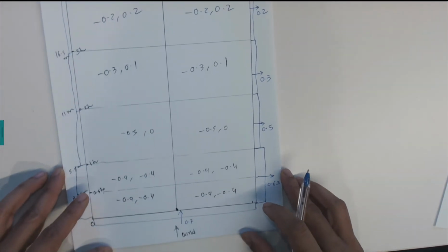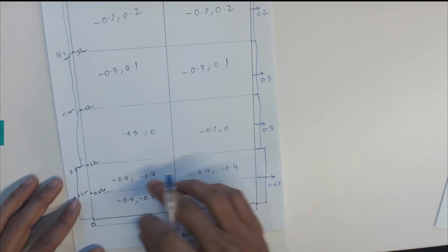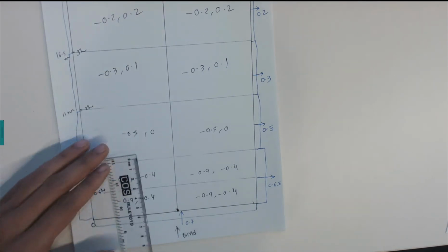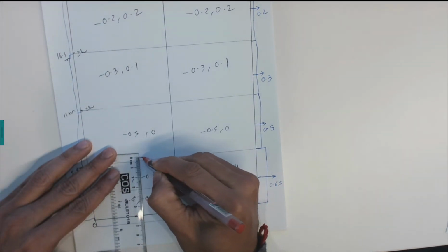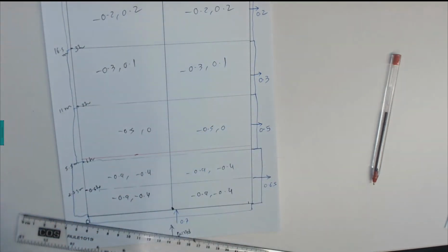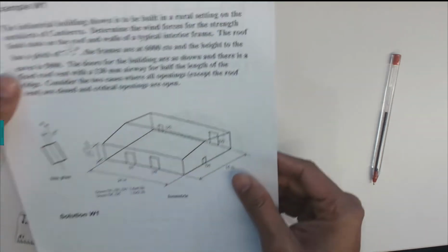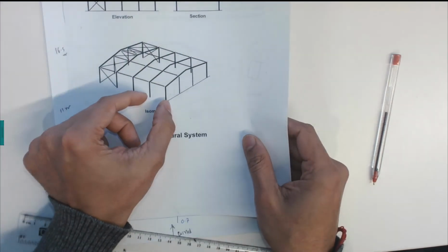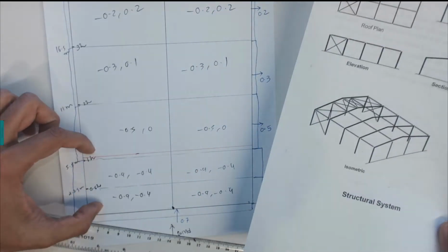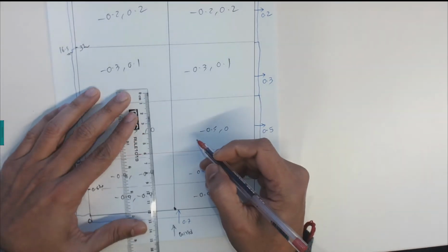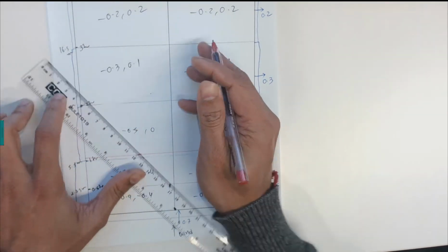Now the important part is that we need to break this down into 6 meters. I can use the red color pen. Because we have a 6 meter portal frame distance, the portal frame has a 6 meters center to center distance, so the distance between these portal frames is 6 meters. That's what I'm drawing here: 6 meters here, and another 6 meters extended onto these levels.